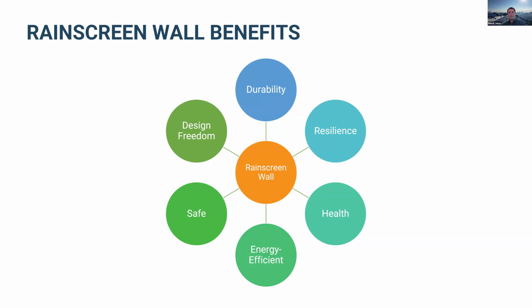Energy efficiency. This is kind of not directly related to rain screens, but a lot of times if we're adding that rain screen assembly to a building, it gives us an easy opportunity to also add more insulation in that rain screen cavity. So we can adapt existing buildings with rain screen retrofits and add exterior insulation, make them more energy efficient.